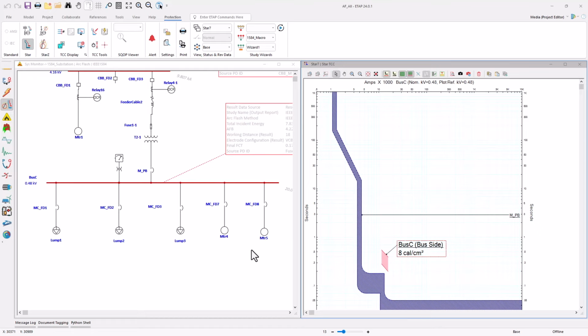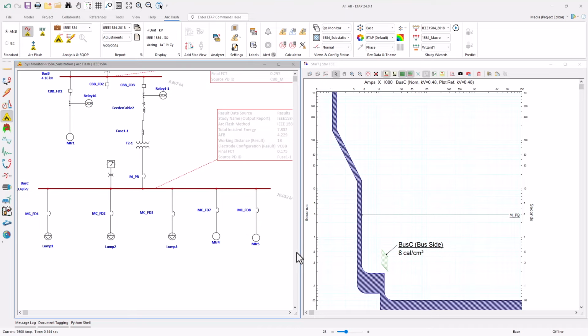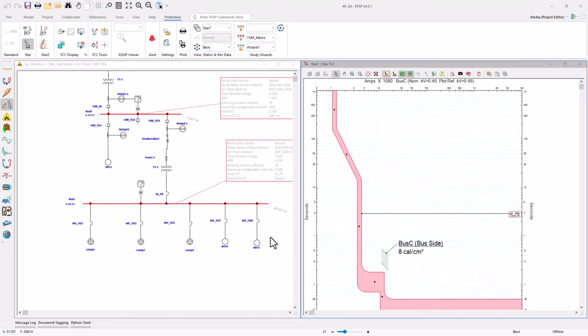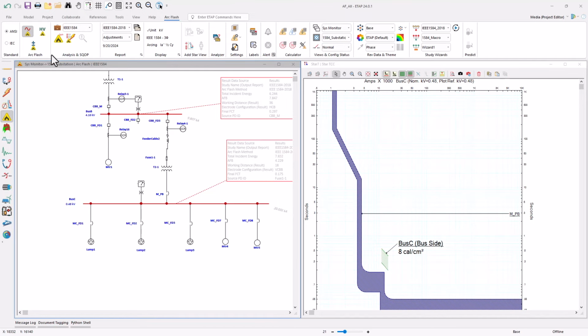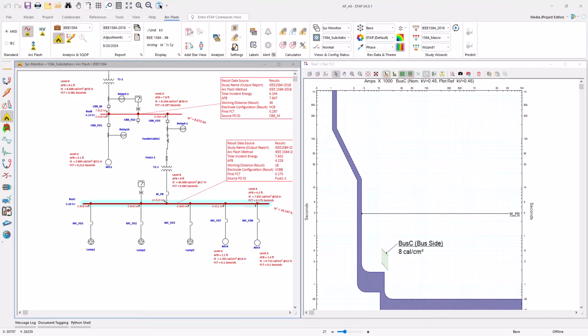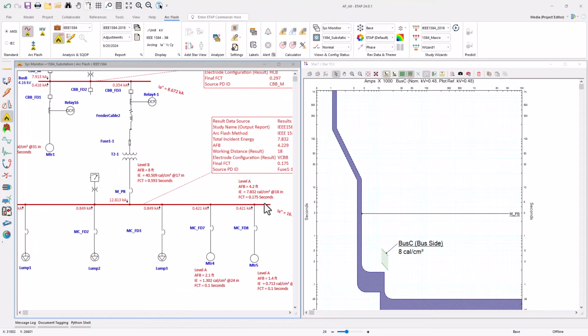If the incident energy reference value is available in the time current curve, it is easy to select the corresponding protective device that is always left and below of this particular constant reference boundary area. And after that, regardless of the calculations and the input parameter variations, the program will give you the incident energy still less than the actual C area, or the constant energy area. By doing this, you save a lot of time and at the same time do not compromise the protection and the coordination settings for the bolted fault current as well as the arcing currents.